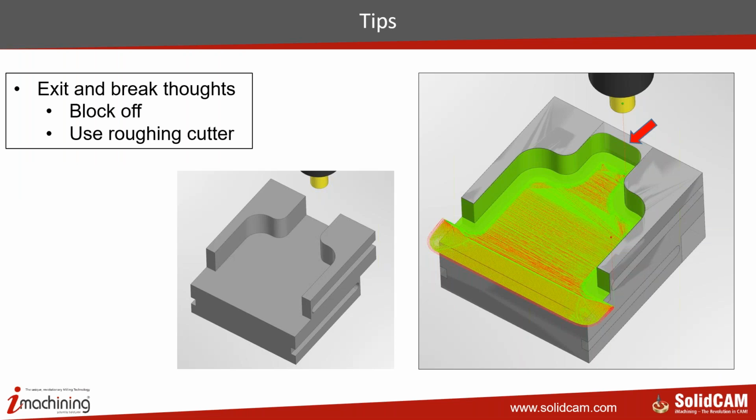Lastly, I'd like to share a tip before finishing the presentation. To avoid problematic breakthroughs into air, it is recommended to block off these areas and use a roughing cutter to break through using an additional operation.